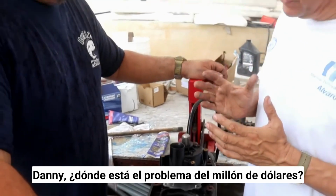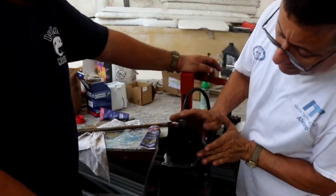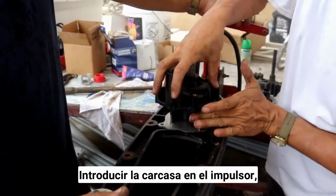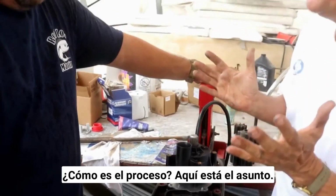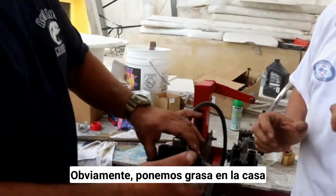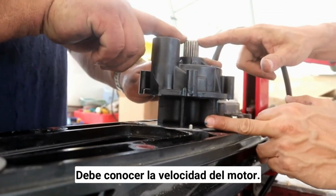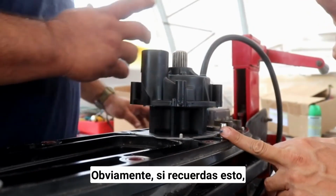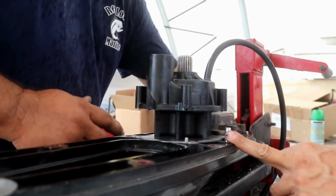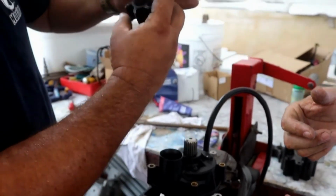Danny, the $1 million question, where people make a lot of mistakes, is how you introduce the housing into the impeller, protecting the impeller. What is the process? Here's the deal. Obviously we put the grease in the housing so we don't damage the impeller, and you have to know the rotation of the engine. It's clockwise. So if it's running clockwise, the impeller has to spin like this, so this has to go in.